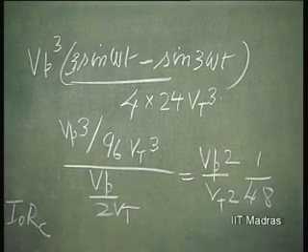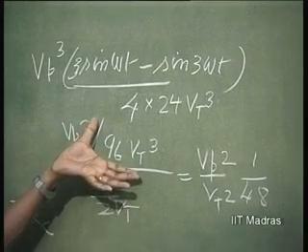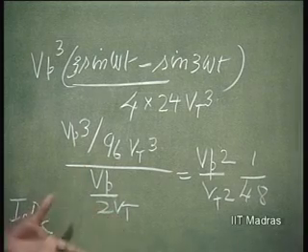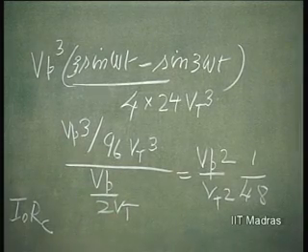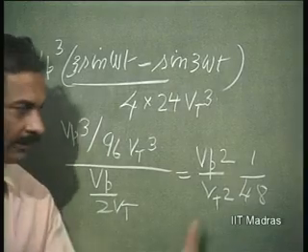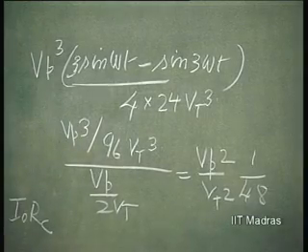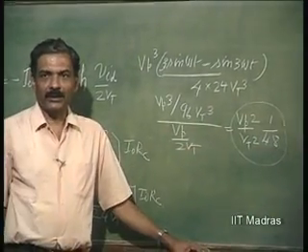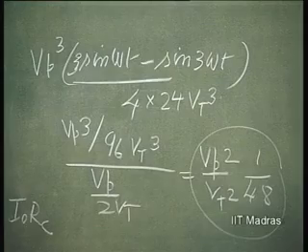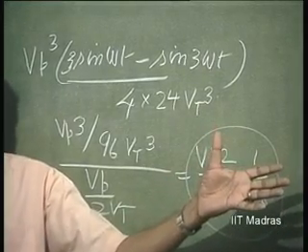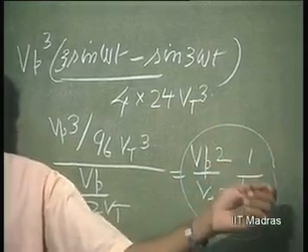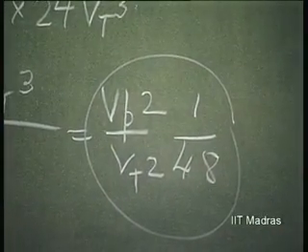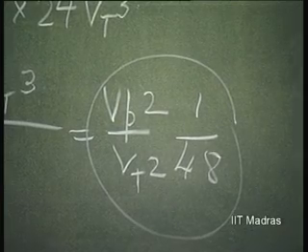So, this is the ratio of the third harmonic to the fundamental. This is also going to be the ratio of the percentage distortion. If you multiply it by 100, this will give you the percentage distortion. So, this will give you an idea as to how to control the percentage distortion in your differential amplifier. This, if it has to be 1%, then this factor should be less than 0.01. Now, that is how you have to control the differential signal amplitude.